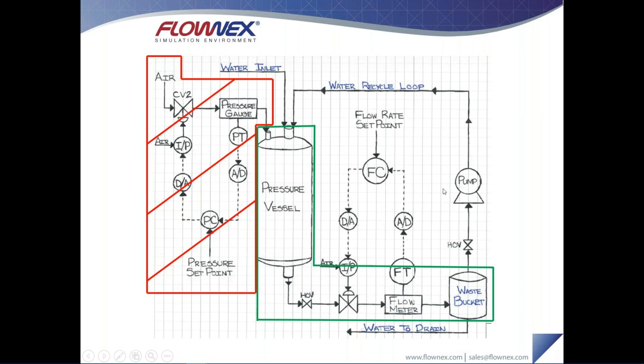We wouldn't need to model the pump and any of the piping at the top here in the recirculation loop before we could actually solve this network. So we could build half of it, test that our network solves, correct any mistakes in our inputs, and then after we've done that, move on to modeling the remainder of our network.